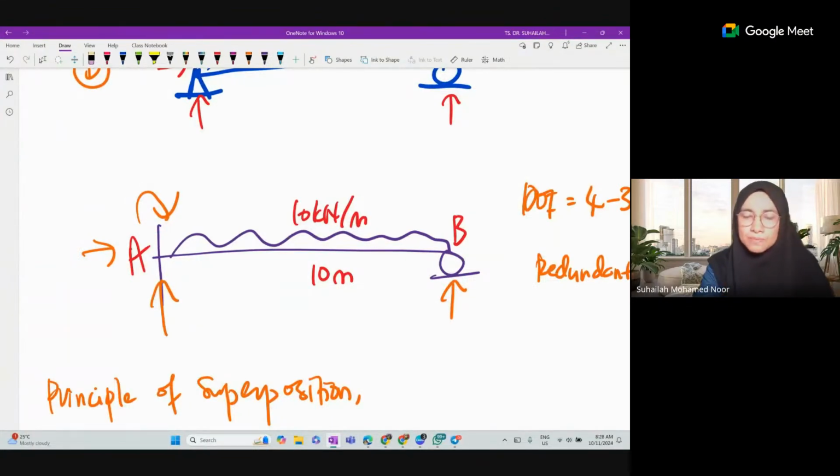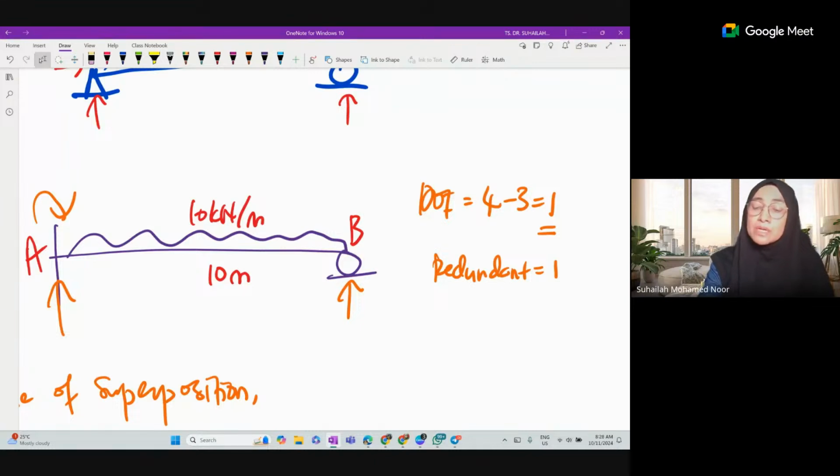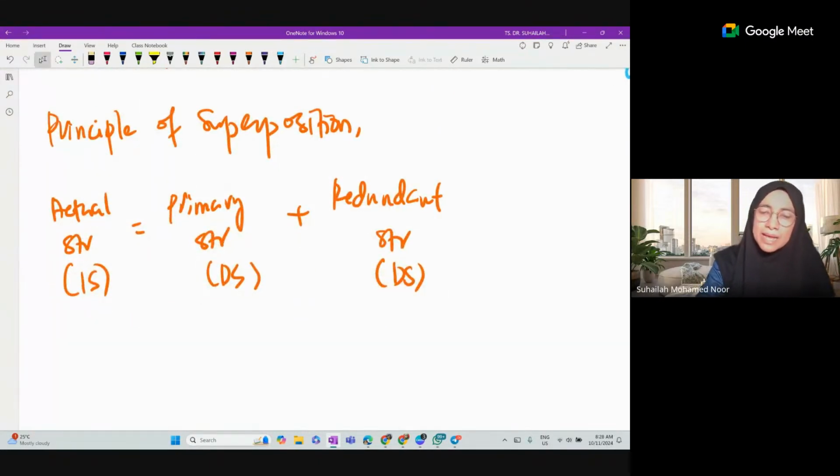Okay, so for analyzing this beam, using a cantilever beam, the redundant can be BY or MA, but we can only choose one as redundant. So let's say we choose to have a cantilever beam, and we choose BY as the redundant.